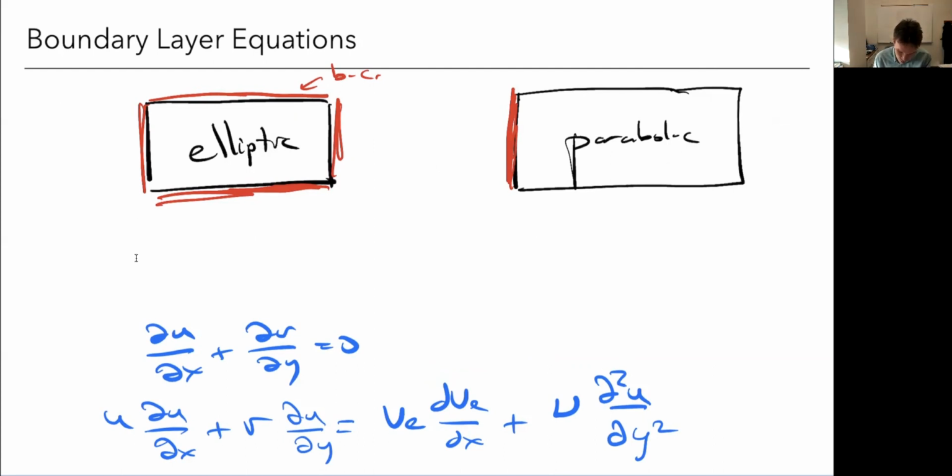First one is called the displacement thickness, and it is given by the symbol delta star. So actually it is going to correspond to this height here. I'm going to call it delta star. So physically what it means is this is the real flow, real viscous flow, right? There's a boundary layer and there is a velocity deficit. So if I looked at the mass flow rate deficit, that's this area in red here. Okay, that's the amount of mass flow that I'm losing from the presence of viscosity.